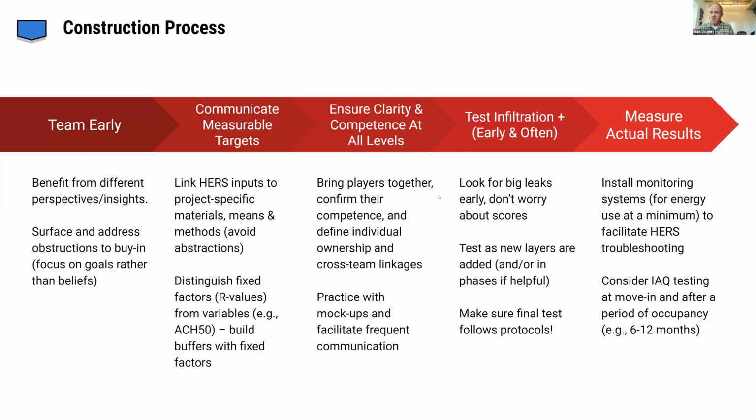And as Mark was saying, it's more efficient to move heat than it is to make heat. If an air source heat pump hot water heater is failing in heat pump mode, but it has the electric boost backup, that just becomes the equivalent of an old resistance electric hot water heater. You can catch things like this if you have the energy monitoring systems. Likewise, you might get a client who calls you because they see their energy bill go up, and now you're in troubleshooting mode. If you don't have that energy monitoring system, it can be pretty difficult to figure out where the problem occurs within the home.